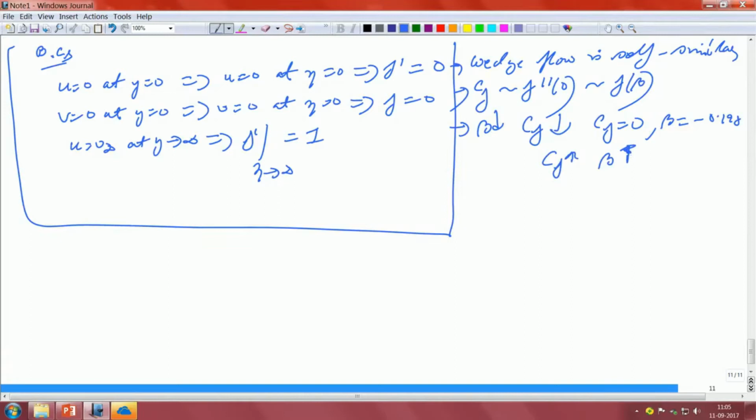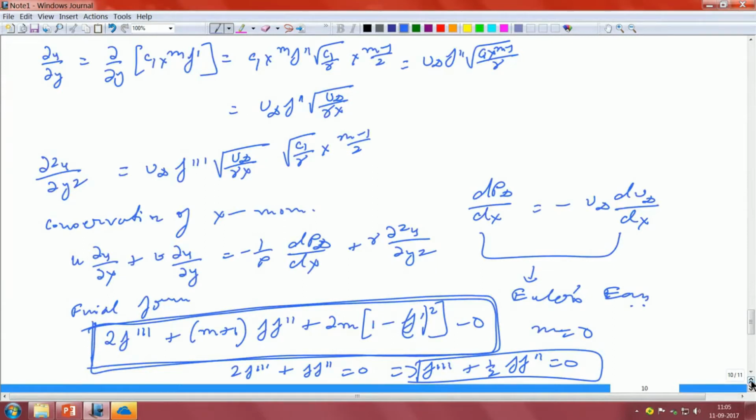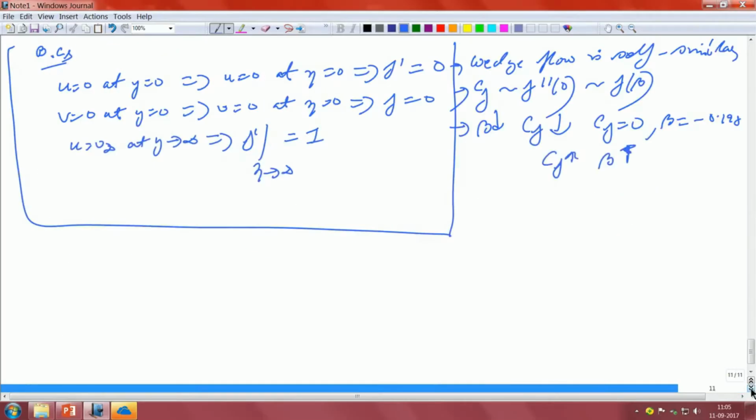If you look at all these mathematical calculations, they yielded the basic governing equation, which we solve in a very similar way as we did earlier, that means using the shooting scheme and things like that. But even without the shooting scheme, the solution pattern remains the same, except that the boundary layer is modified depending on the value of m. Remember, m is your beta, and the special forms can all be derived from this expression.